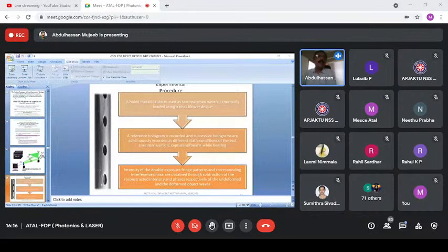Now I want to detect the voids, that is the defects, in this cylinder. I have to take the holograms of this metal tube. A hollow metallic tube is used as a test specimen, which is thermally loaded using a heat power device.